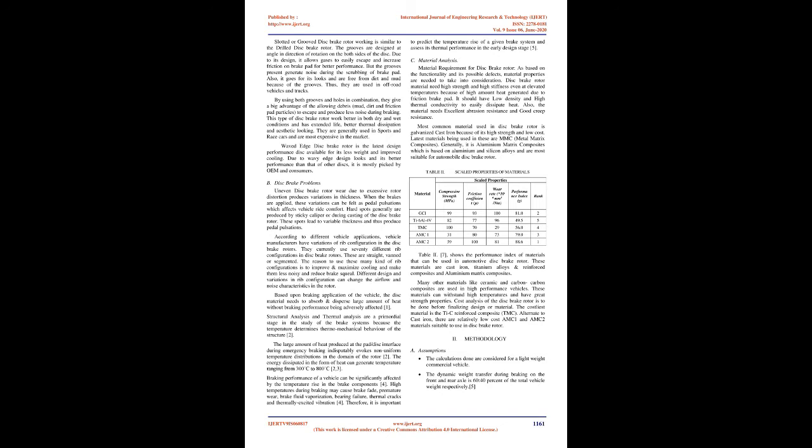By using both grooves and holes in combination, they give a big advantage of allowing debris, mud, dirt, and friction pad particles to escape and produce less noise during braking. This type of disc brake rotor works better in both dry and wet conditions and has extended life, better thermal dissipation, and aesthetic looks.